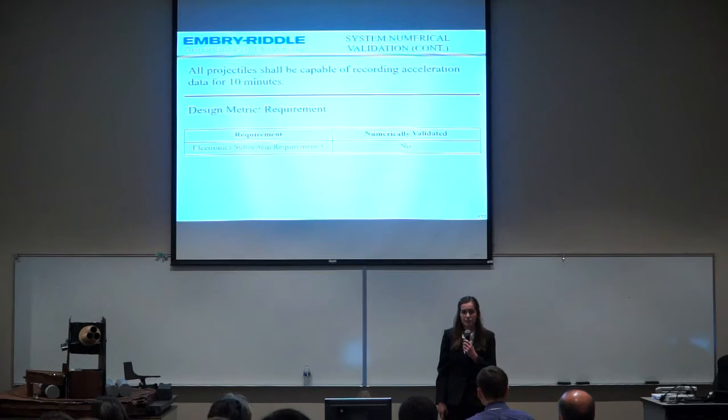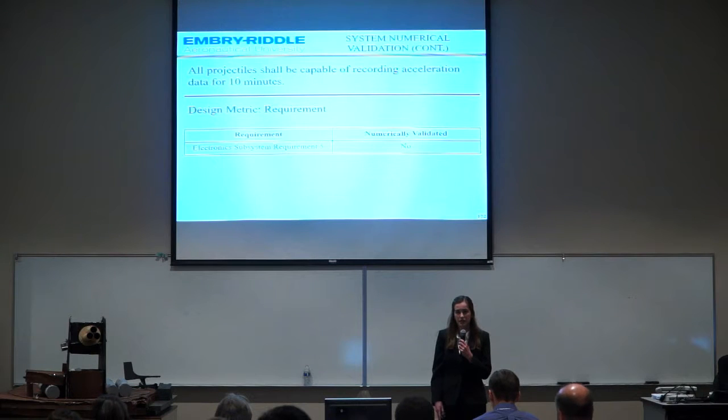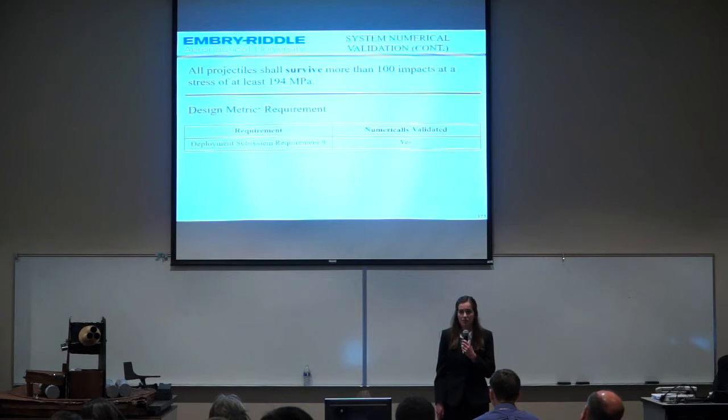Next, all projectiles shall be capable of recording acceleration data for 10 minutes. This has not been numerically validated by the electronic subsystem due to the fact that we do not have certain information from the manufacturers as to whether or not some of the electronics will survive an impact. Next, all projectiles shall survive more than 100 impacts at a stress of at least 194 megapascals. This has been numerically validated by the deployment subsystem.